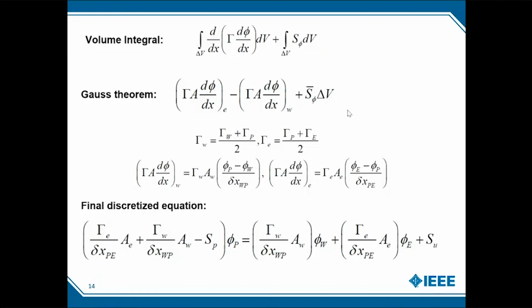Whenever people do CFD analysis, they use particular numerical schemes. What I have shown you over here is just a simple numerical scheme in which, for example, you see dou phi by dou x. We just use this particular simple approximation, but this, to be honest, is not really accurate. It might work well for such a simple problem. For a more complicated problem, approximating this differential just as a finite difference approximation will not really work well.